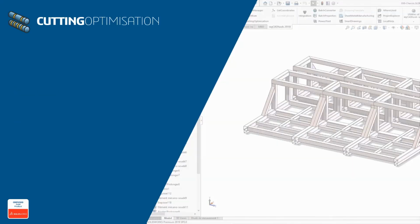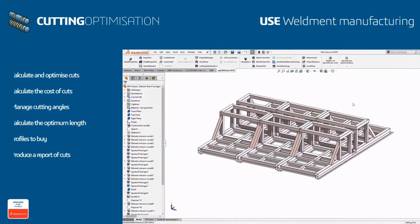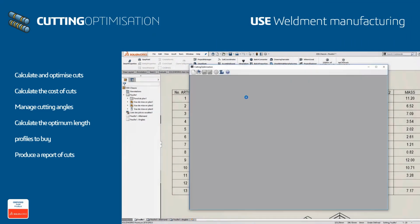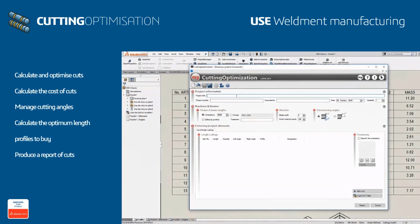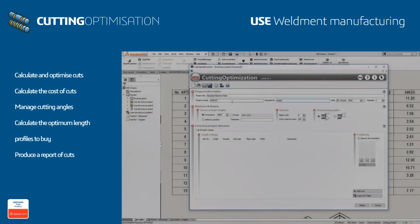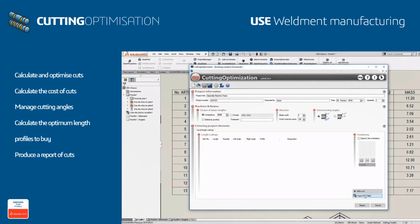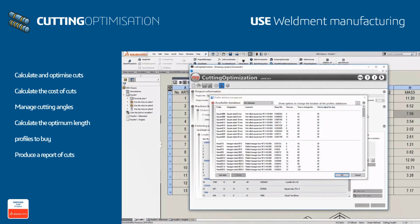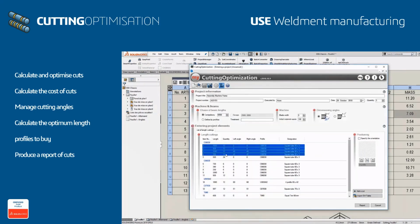Cutting optimisation. If you work with welded frameworks or any design that use profiles, cutting optimisation can help you understand the best stock lengths to purchase and also optimise your cutting schedules. Simply select a SOLIDWORKS weldment cut list to load into the tool, and the software will read the information from the database. If you are manufacturing more than one item, a quantity option is included.